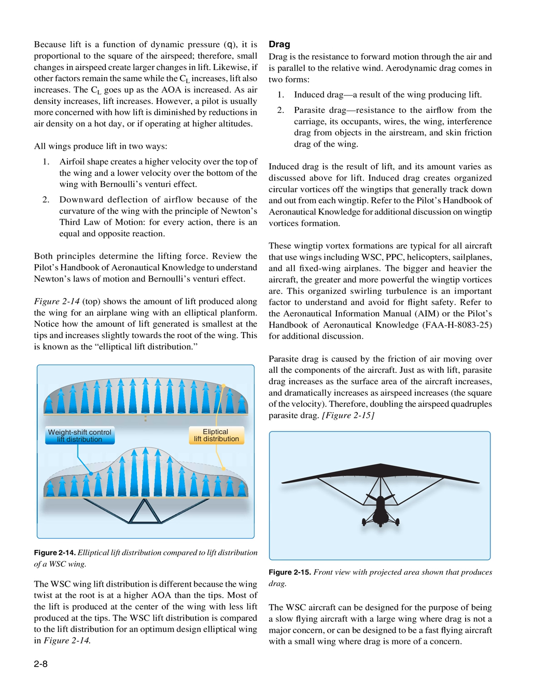Because lift is a function of dynamic pressure Q, it is proportional to the square of the airspeed. Therefore, small changes in airspeed create larger changes in lift. Likewise, if other factors remain the same while the CL increases, lift also increases. The CL goes up as the angle of attack is increased. As air density increases, lift increases. However, a pilot is usually more concerned with how lift is diminished by reductions in air density on a hot day, or if operating at higher altitudes.